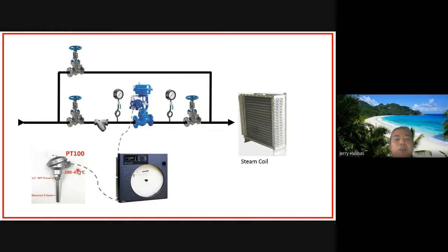Your PT100 or RTD is also connected to the temperature controller. Then the output goes to the steam, next into the steam coil.